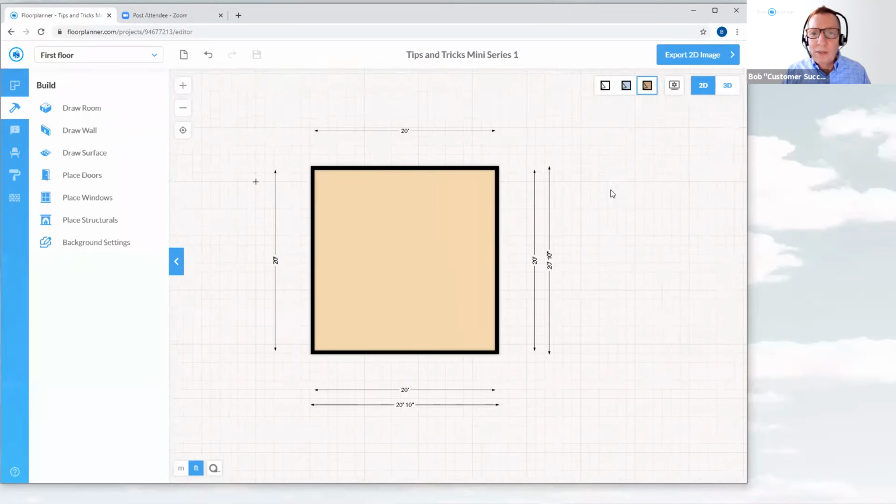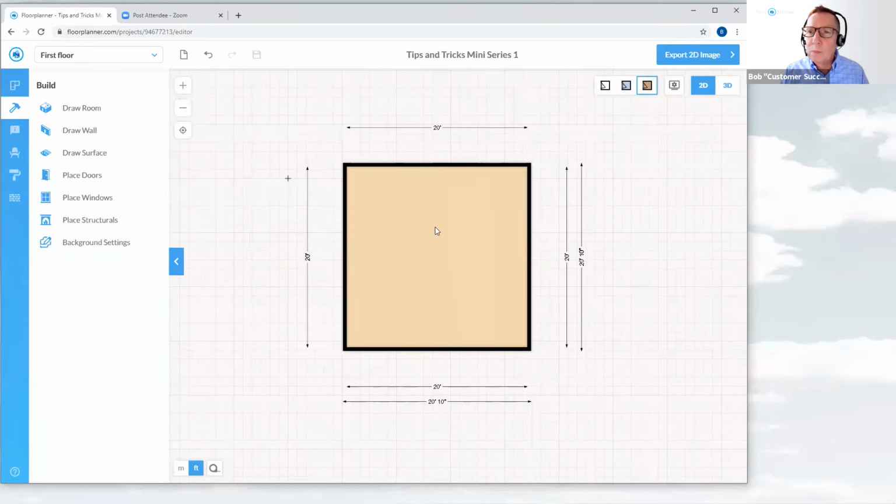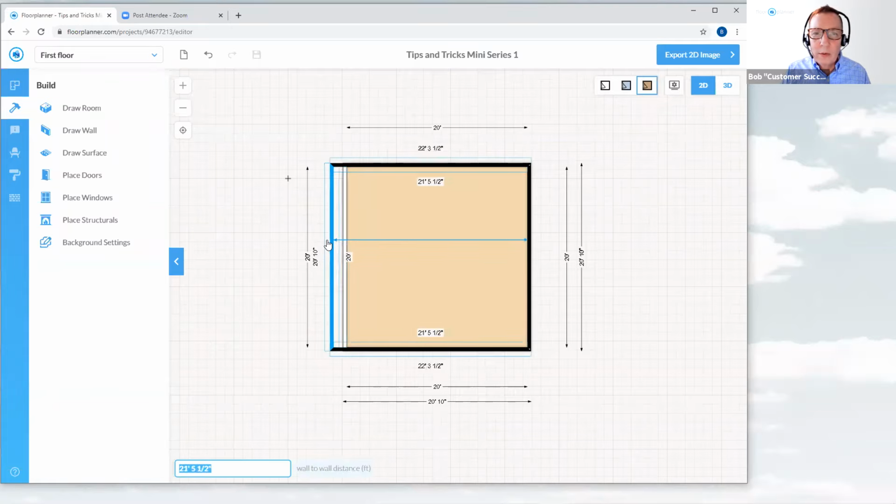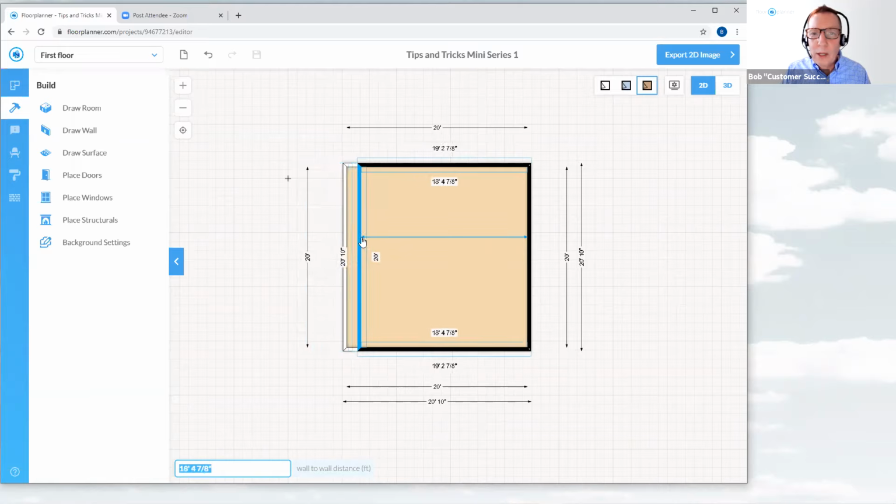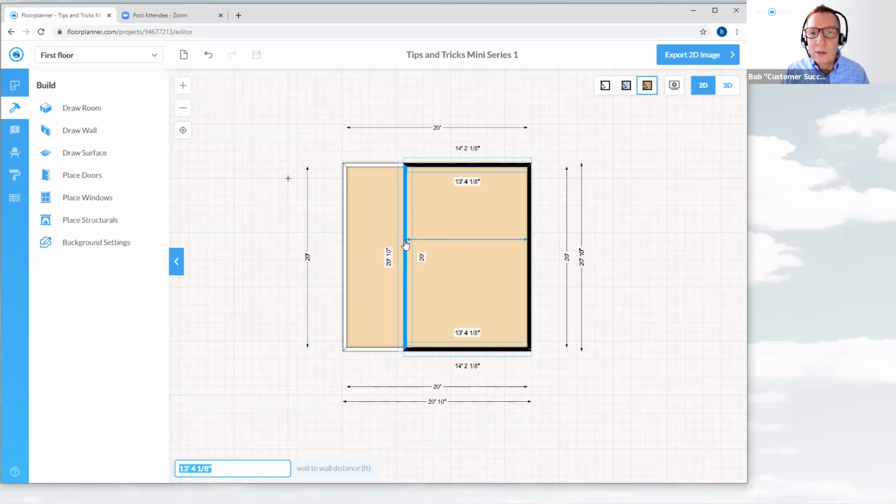I want to show you something else, that sometimes you may have an interior room that you don't have the dimensions showcased around. It could be an interior closet, and you need to make some sort of change in the size. So let me show you how you can actually, because you always want those exact dimensions. Like, how can I move that exactly the right dimension? You can drag any of your walls out also. So if I select a wall and I left click on that wall when it's identified, I can start pushing in any direction. Now you can see the blue line appearing in the very center for the dimension line. You can see that its dimension keeps changing for the interior dimension.